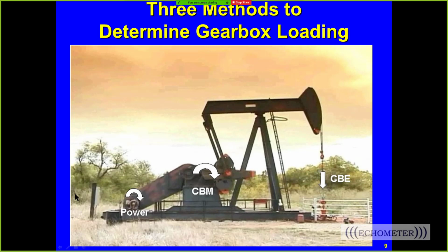And then the third method, which we call method 1 on the previous slide, is measuring the power with the power probe inside the panel. We just measure the kW, and the kW is directly proportional. It's a pretty simple method. It's easy to do as long as you have an electric motor.